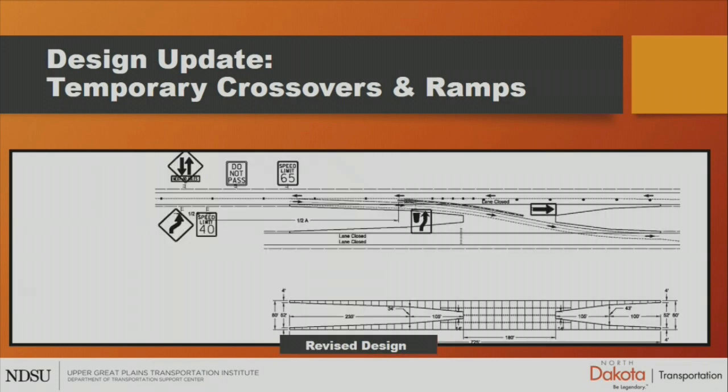But the new design is considering a little bit shorter. It's 725 feet overall instead of 800. We'll have a speed limit regulatory sign rather than an advanced warning sign there. It'll be posted for 40 rather than a warning sign for 40. And then we use almost half as many barriers, I think 47 precast barriers with the shorter transitions. So again, it'll be shorter overall crossover length, almost half as many barriers, and then the signing is a little bit different.